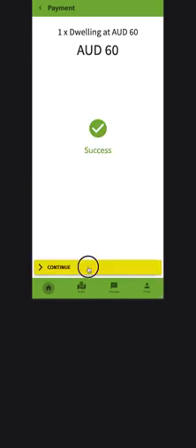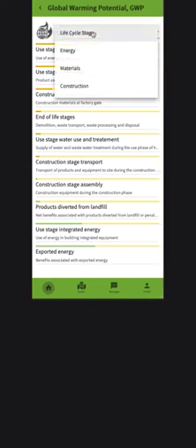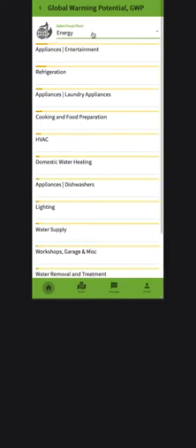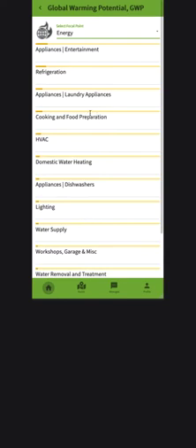Okay, so yeah, that's succeeded. So I can now drill down into the results to see what was driving the remaining global warming impacts. And I can look at this using different focal points. So focus in on energy. I can see this is that big positive impact of the PV, the solar photovoltaics. And my remaining items are actually, there's a lot of plug loads there, which is pretty hard to influence as a building designer. The cooking is fairly high. Heating, ventilation and cooling is pretty big.